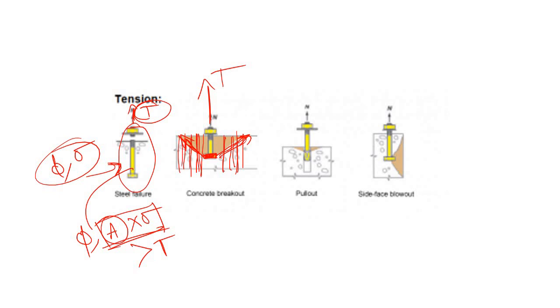So if you have also resisted the vertical crack, then what can happen? Simply the concrete will remain intact, the bolt will remain intact, but the bolt will simply come out due to this tensile force, and this is known as pull out. So to resist this pull out, what you have to do?